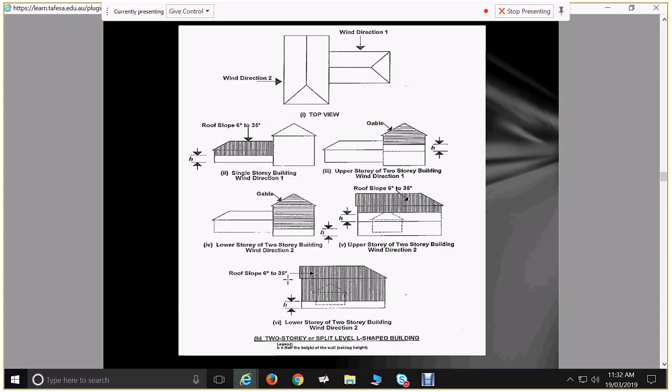This is how we go about calculating our bracing. So we have to look at the wind forces acting upon the building. The way the Timber Framing Code sets out our process for working out the way wind forces are acting on the building is to take in the whole vertical elevation area of our roof plus half of the vertical elevation area of our wall. So we take that in and go, that's how many square metres it is.